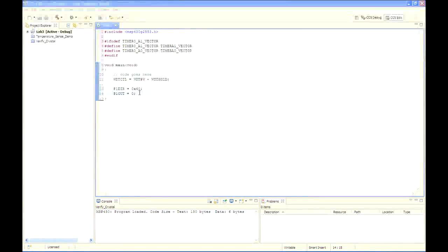In step 6, we're going to go ahead and set up the clock system. Enter a line for spacing and then type the basic clock system control register 3, and then LFXT1S underscore 2. So that register is one of the basic clock system control registers. In the user's guide, section 5.3, it tells us that the reset state of the register is 5. Check the bit fields of the register and notice that these settings are for a 32 kilohertz crystal on the clock input pins with 6 picofarad capacitors and the oscillator fault condition set.